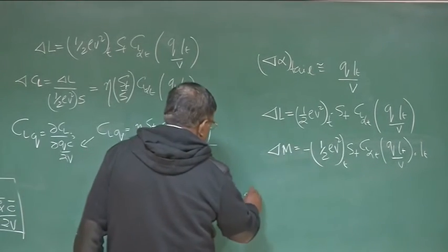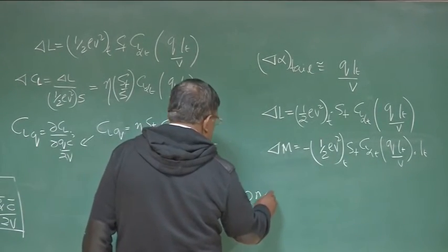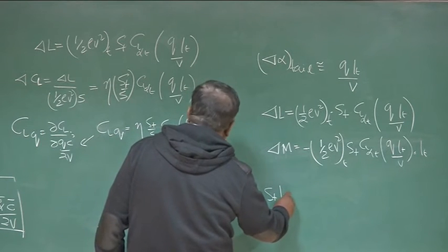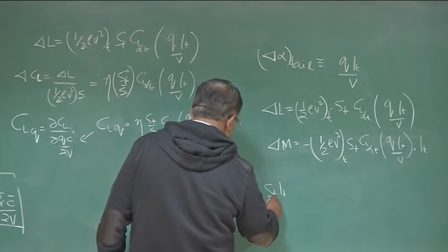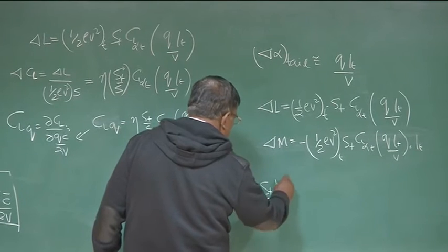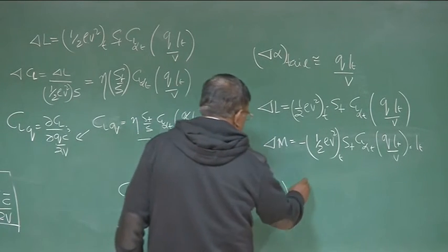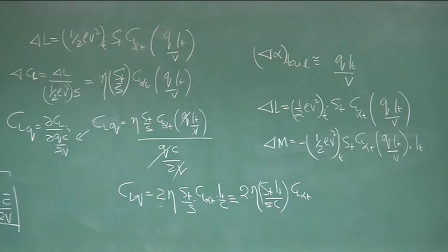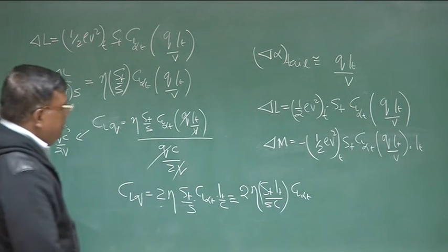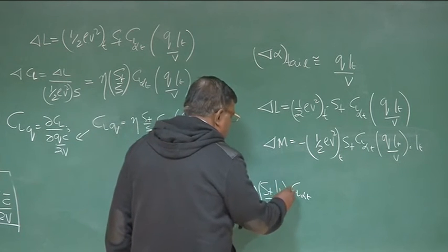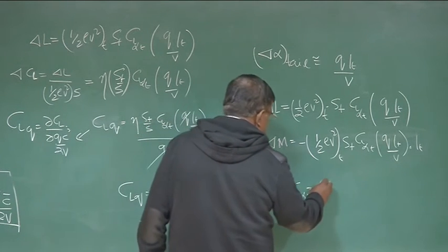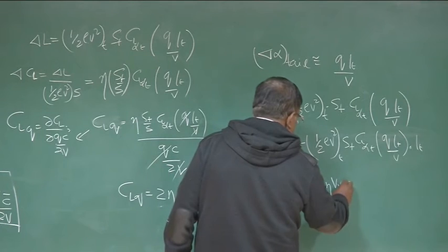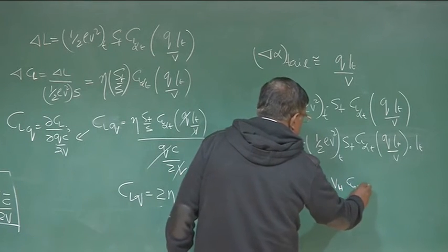by now you are expert, you know the way to write this: ST LT by S c into CL alpha tail, correct? 2 eta. Are you familiar with one of the popular expressions? This is the popular expression, and that is 2 eta into VH into CL alpha tail.